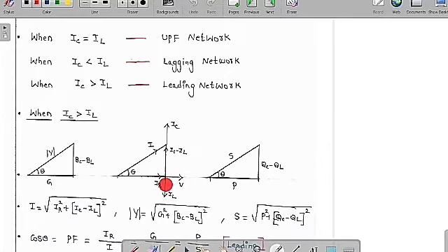So this is IR. But in an inductor, the current is going to lag, which is IL. And in a capacitor, the current is going to lead the voltage, which is IC. I have assumed that IC is greater than IL. Therefore, the overall vector addition will become IC minus IL in this direction. If I add these two vectors, we get the overall supply current. You can see clearly the overall current is leading the supply voltage. It indicates that it is a capacitive network. So this is angle theta.